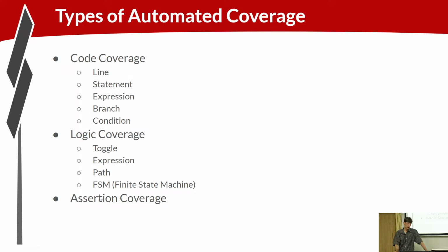And assertion coverage. In addition to expressing logic, your code is expressing assertions, which we just mentioned. You can make sure that the properties you're defining for your assertions, the temporal logic that you're expressing in those, is exercising all the temporal steps. The assertions might be asserting state transitions, so make sure those transitions are happening, things like that.